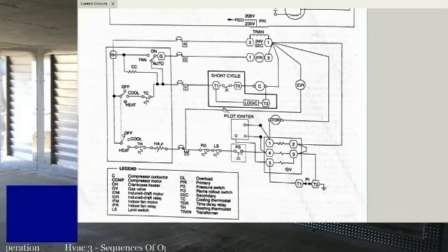So obviously, if nothing's happening, you have to start back at, do I have power in? Is there a signal at the W terminal or the white wire, depending on how they ran it? Usually your white wire, W terminal. So is there power there coming back to the unit? And then what happens from there? But if we read this furnace sequence, or this heating sequence of operation, we'll be able to understand, okay, what's happening when something goes wrong.